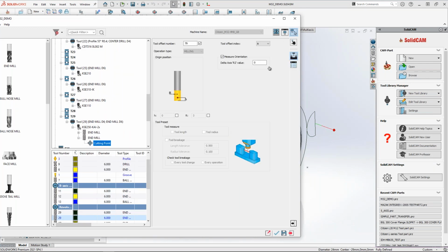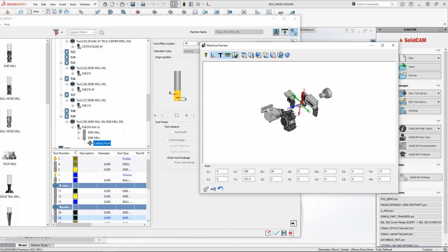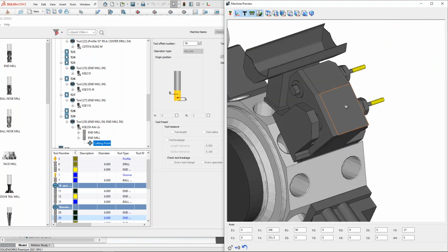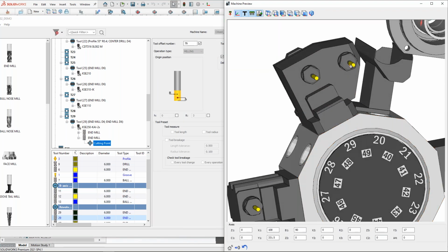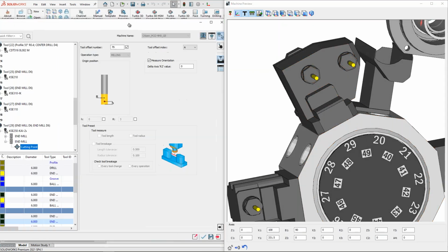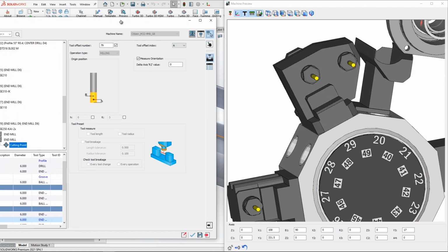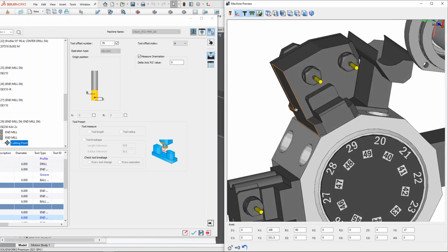I will go to the cutting point, and now this is a little bit of small details. What will be the index angle? On every machine you have to do it differently, so you will save this data per turret. There is one way how to do it. Also, the folder shows everything by itself. So you can go to the measurement, click there, click here, and you'll get the angle of 18.